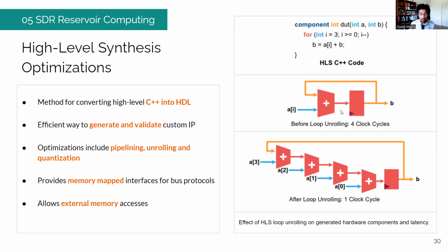So compared to the first approach, there are 4 different adders that are used in the unrolled approach. So even though you get a faster circuit, you trade that off with more area that's being used. And that's a common trade-off that designers make when creating these different hardware implementations. It's a trade-off between parallelism and the actual area that's being utilized.